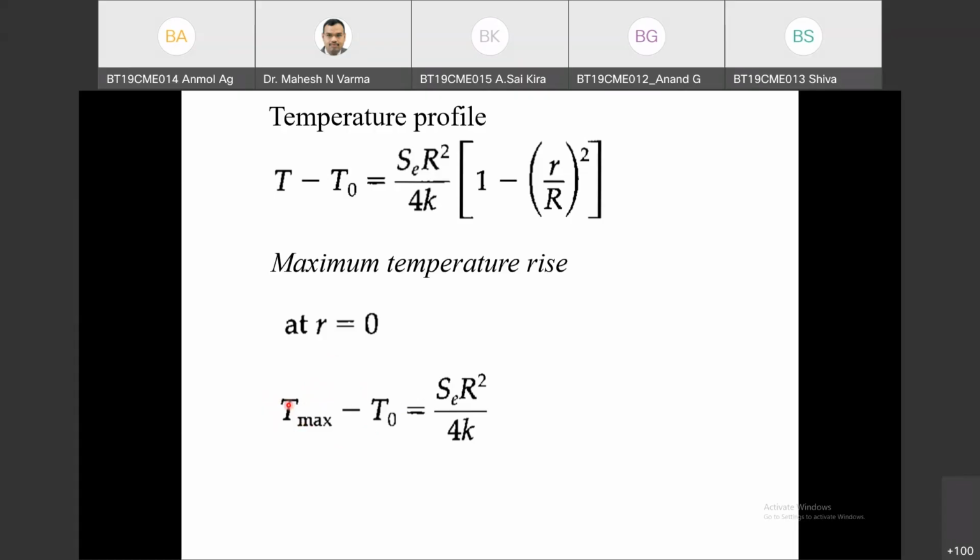Hence you will see that high current flowing wire, called a high tension wire, has a different insulating material because its heat generation is higher compared to the heat generation in our household wire. And the cost of the wire will also vary based on the polymer you are using for the insulating material. And this is a very important property, based on the maximum temperature which can be attained given a current intensity and